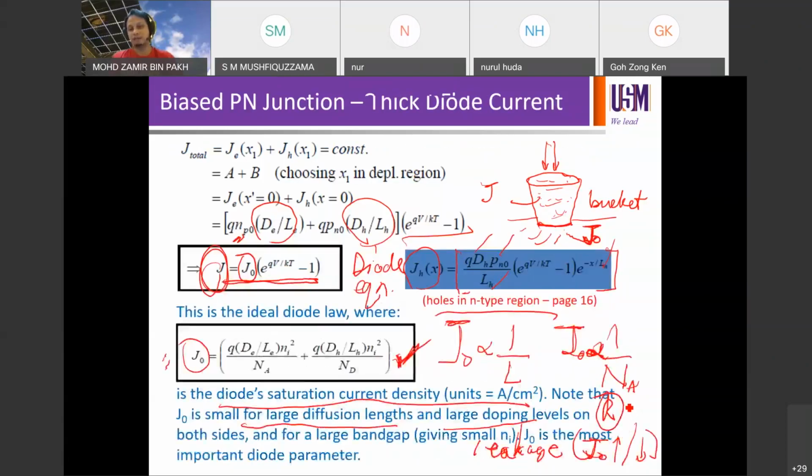To be more specific, which recombination increases? We learned about the three recombinations, right? Which one increases as you increase your doping level from 10^16 to 10^19? Traps, yes, you increase defects. But what's the most prominent one out of the three recombination mechanisms at high doping level?